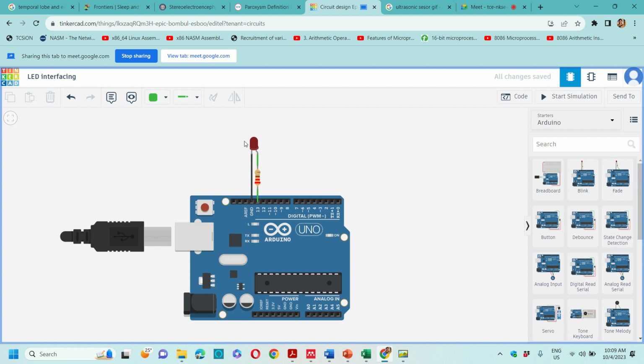Okay, now LED. When I am talking about LED, how to use an LED? While using an LED, if you click over here on each of these terminals, it indicates whether it is a cathode terminal or an anode terminal, right? When practically you visualize an LED, in lab also I have told you how to recognize it. The length of a terminal of an LED can be used to identify the cathode and anode.